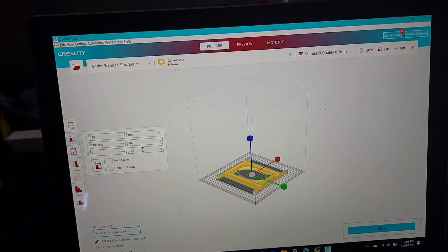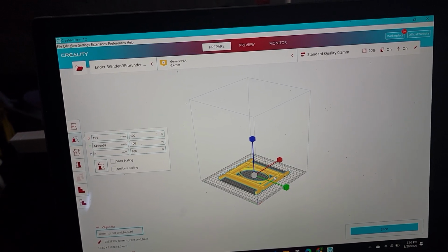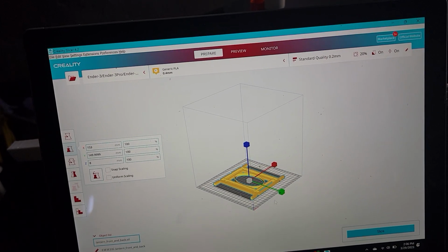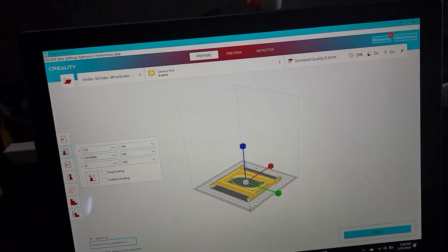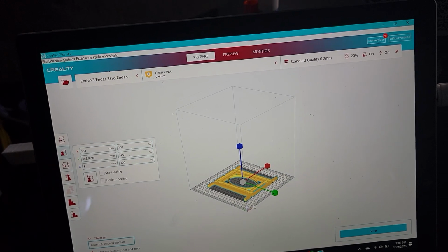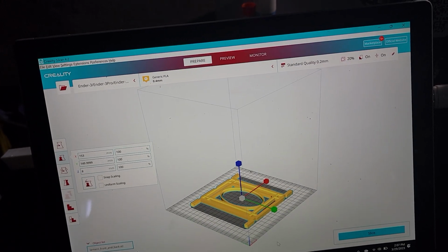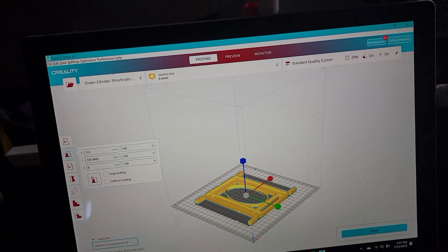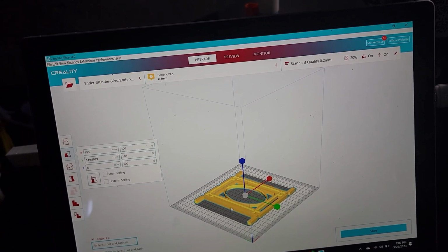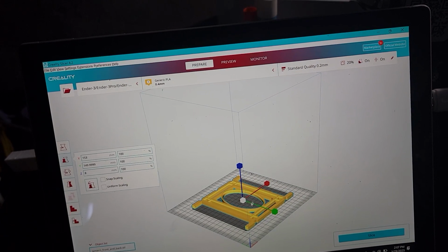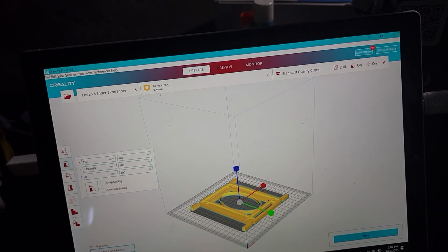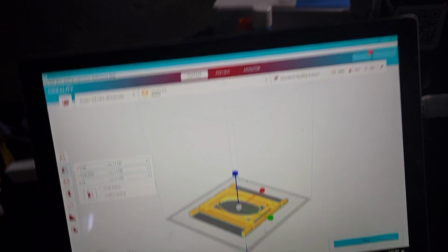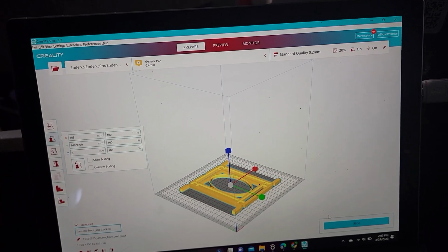If it is too big, it will not print, but it will print because there is spacing around the sides. You do not want to go past this gray line, as if you go past this gray line, it will not allow you to print the file. So, since everything is fine, it now has the most surface area on the plate and is not extending past the gray box, I will select Slice.